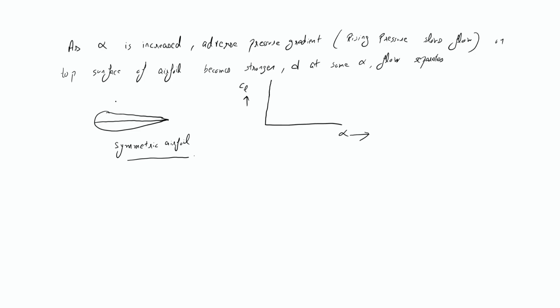Because here, at the same point, for example, we have the top force F, and at the bottom we have the same force F. So both are exactly balancing out each other, and there is no movement. So because of that there will be no lift at zero angle of attack. Rest of the curve remains similar. So this is alpha equals 0 degrees. At alpha equals 0 degrees there is no lift. This is applicable for the symmetric airfoil.